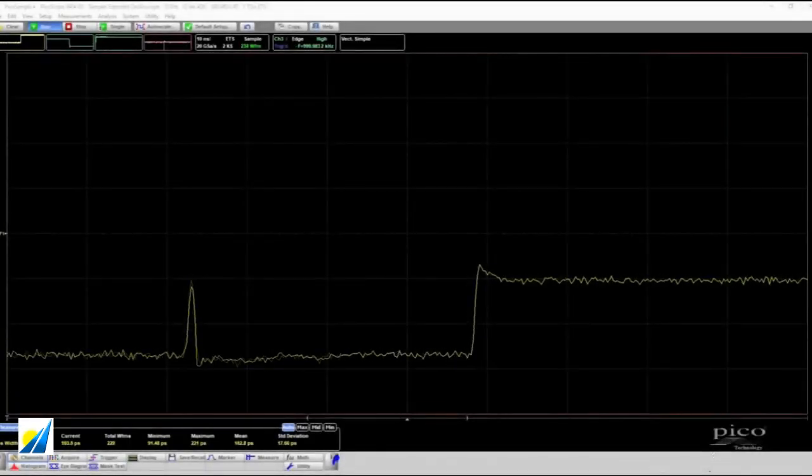However, those relatively high speed A to D converters and the very expensive memory bandwidth still doesn't get us all that we might need in a real-time oscilloscope. If we consider the narrowest pulse that a 5 gigahertz oscilloscope would be able to capture, that would be a 150 picosecond pulse or data interval. If we capture that at 20 gigasamples per second, we're just going to get 3 samples within that pulse, and the fidelity of its reproduction is rather lacking.